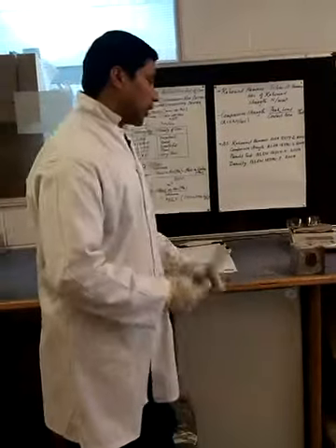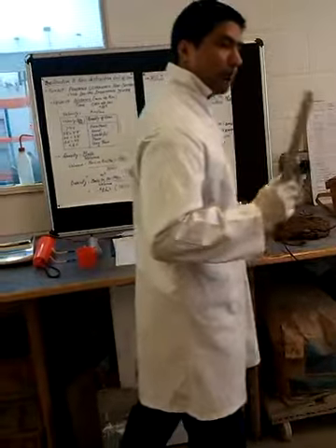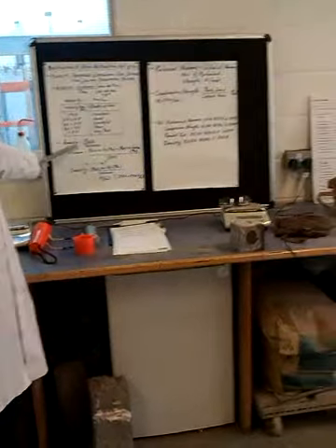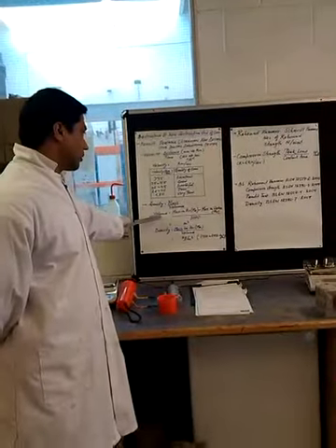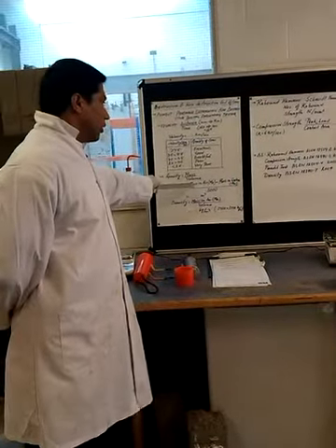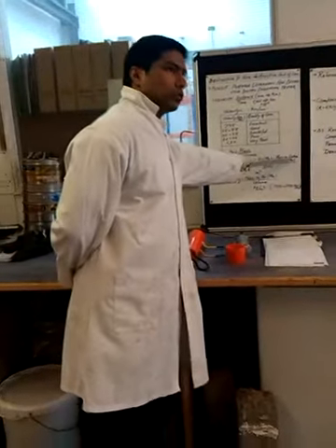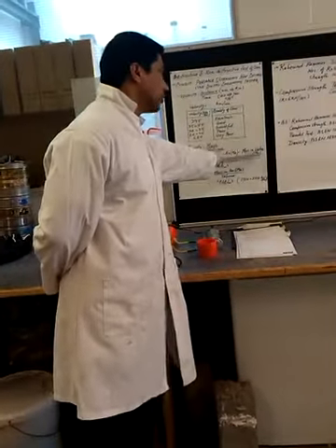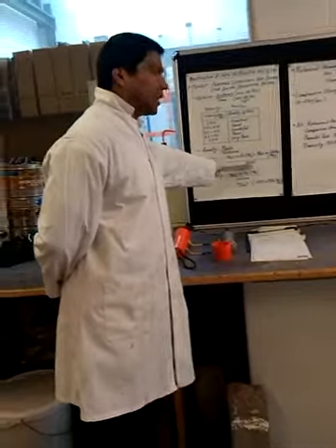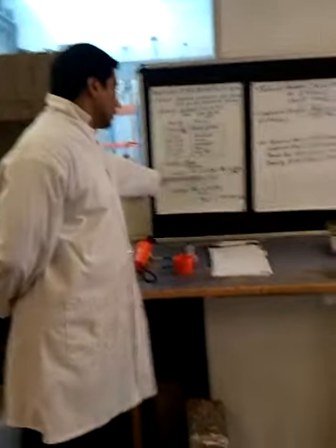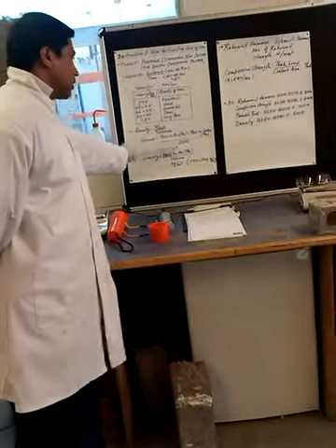Okay, so we are going to do the water displacement method, in which we need to follow some steps to calculate the density. First, we will calculate the volume. For volume, we need the mass in air and mass in water. So mass in air minus mass in water, divided by the density of the water, which is 1000 kg per meter cube. That will give you the volume in meter cube.